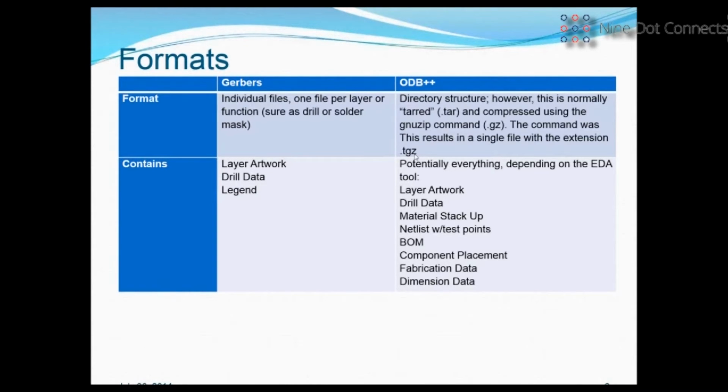The only reason I bring that up and go on that tangent is that when I worked for Altium, we got calls all the time from customers in a panic saying, my manufacturer can't use my ODB++ files because you're not putting it in this format. And I have to call the manufacturer and tell them, no, you just have to point it to the directory after you unzip it. It's fine. But they got really panicky if they didn't see this particular extension. But that's what the extension's all about for those people who are not familiar with Unix.